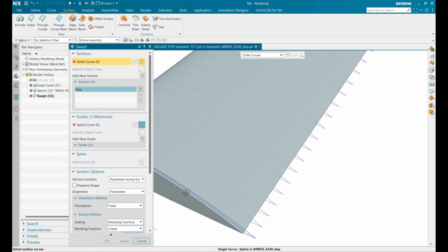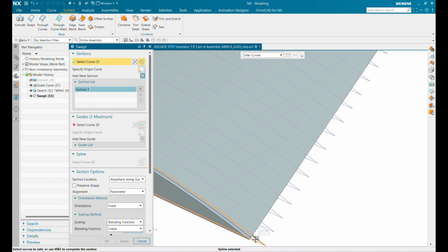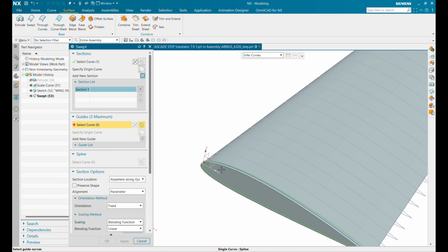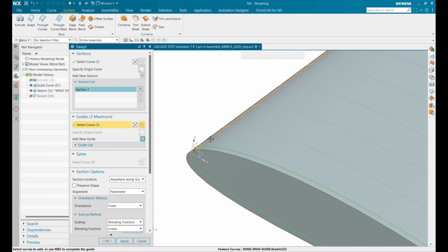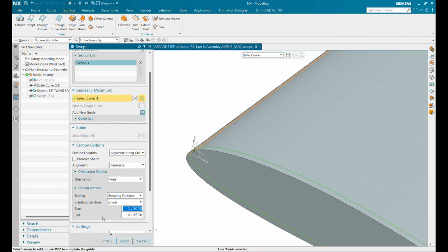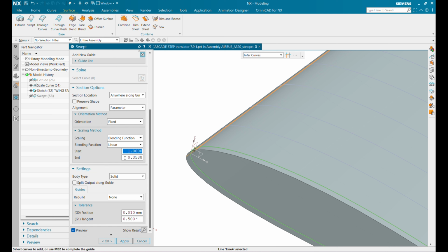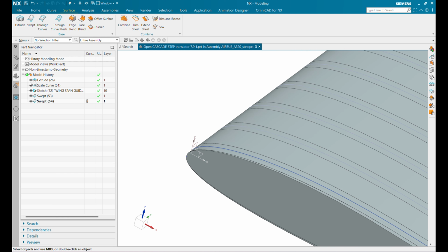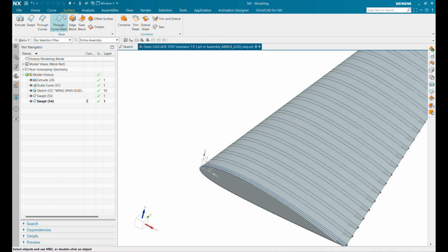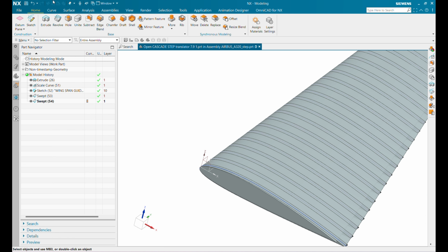Now what we want is another solid sweep. So we select the other airfoil curve along the same guide, same taper, and again 2.3 by 6.5 here. So we've got two solid bodies and we want a hollow body, so we'll perform a Boolean operation here.